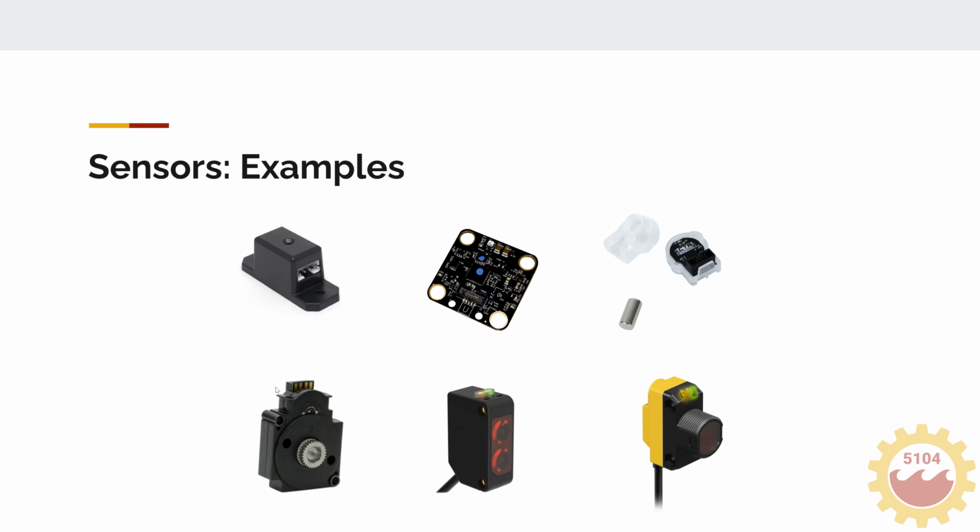Now this is basically the same thing. It's literally the same encoder but flipped sideways and put vertical. And so this port's right there if you can't see it. This doesn't support CAN. This only supports plugging directly into a Talon SRX. But this is a VersaPlanetary slice. If you know what a VersaPlanetary is from VEX Pro, you just put in a little slice and it can detect the position.